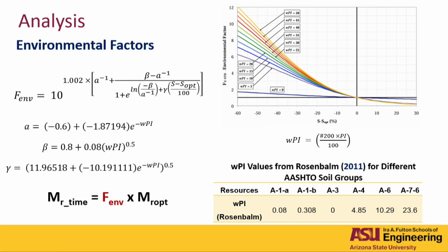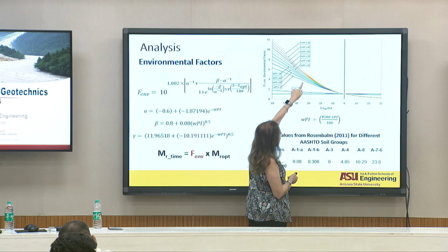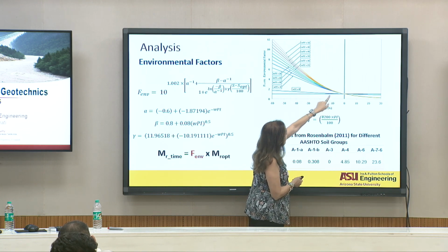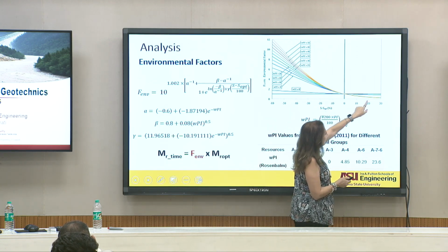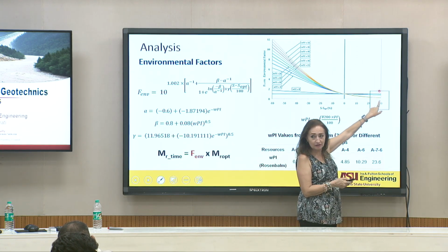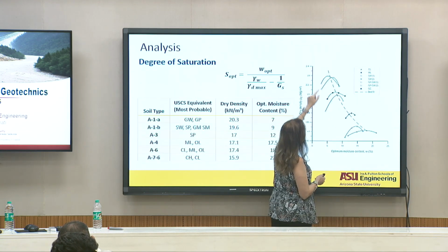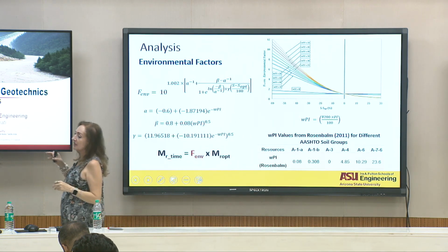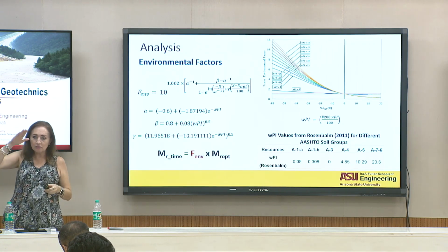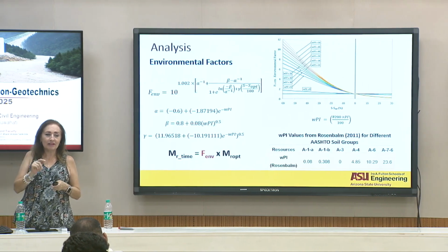So if you have an A6 soil, with a PI probably about 20 here, if you went from a value at optimum condition and the reduction came because you went all the way to here, very saturated, you need to dry it again. But I guess it will recover. The analysis is that resilient modulus means elastic modulus. Good question. It makes me think about that.